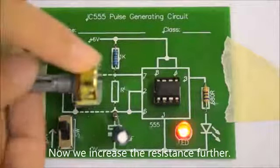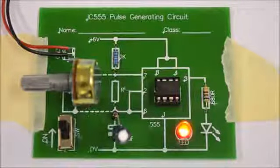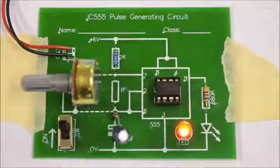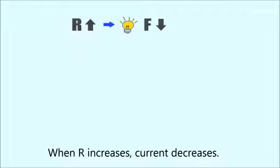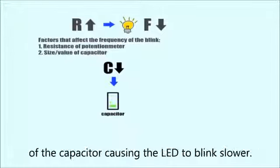Now, we increase the resistance further. Notice that the frequency of the blink decreases. If you increase the resistance even more, the blinking gets even slower. When R increases, current decreases. Therefore, it takes longer time to charge up the capacitor. This results in a slower rate of charging and discharging of the capacitor, causing the LED to blink slower.